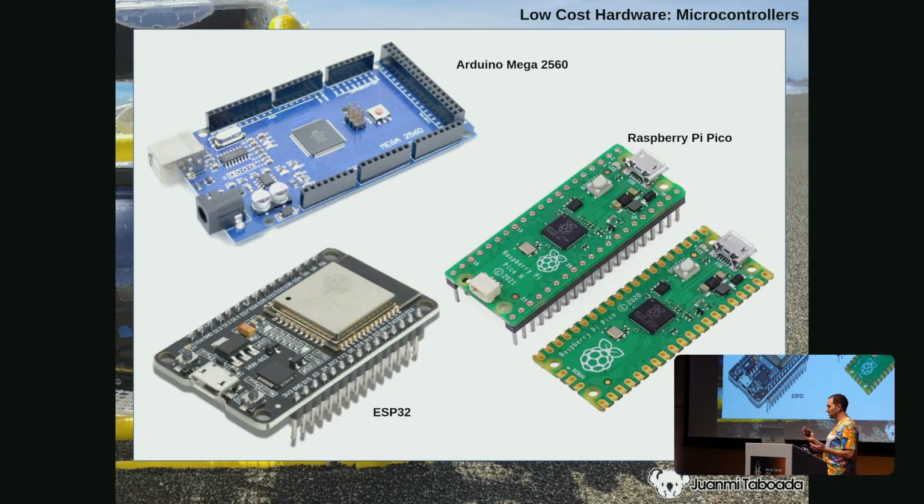So I moved the reception of the commands from the Arduino Mega that was under the ROV, because for me the buoy was a gateway, and I had to move it to the top line. So all the logic now is happening in the top line. The MAVLink protocol is being processed on the top line of the water in the buoy, and the buoy is sending very simple commands in binary format to the submarine, and the submarine is responding that way also.